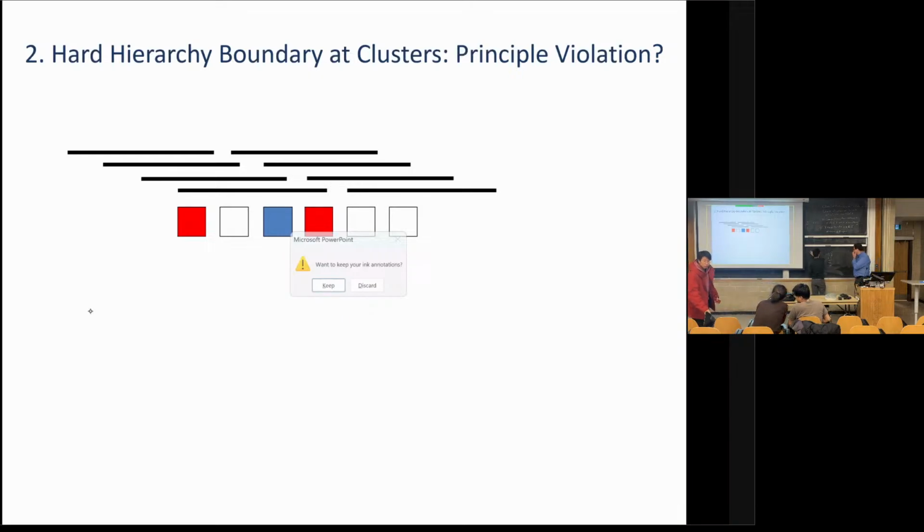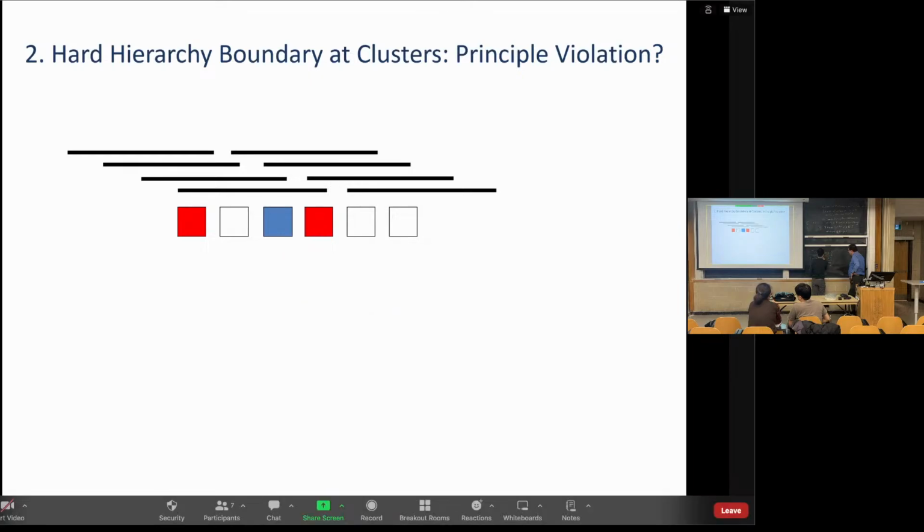I was trying to draw the picture before. There's some pattern, and you're going to have the same pattern down here, which is what you were showing before. Yeah. All right, okay. And they'll connect. So basically what I'm saying is, let's say the first one connects like this. The second one, you do this. Connect offset by 1. Yeah, and then basically the same pattern here. And so what you're guaranteed is, because of the permutability of the mux, of these LUT pins, these are logically equivalent, if it's a LUT. Yes. But because these pins are different speeds, you can now potentially get a speed up just by swapping these two, which you couldn't get before.